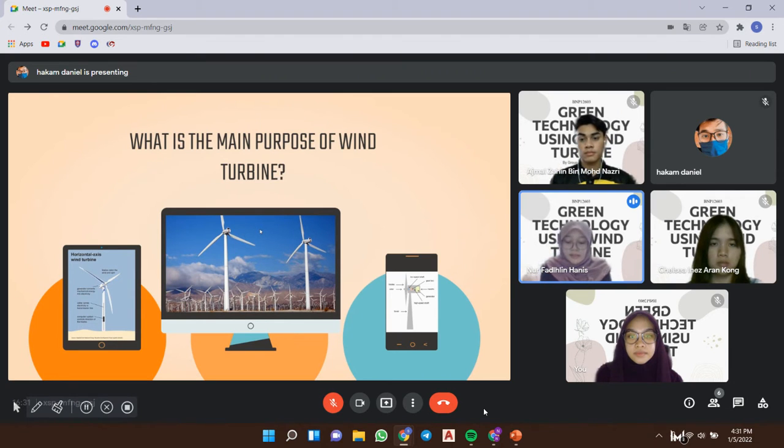When wind flows across the blade, the air pressure on one side of the blade decreases and difference in air pressure across the two sides of the blade creates both lift and drag. The force of the lift is stronger than the drag, and this causes the rotor to spin. The rotor connects to the generator either directly or through a shaft and a series of gears that speed up the rotation and allow for a physically smaller generator. These translations of aerodynamic force to rotation of a generator creates electricity.